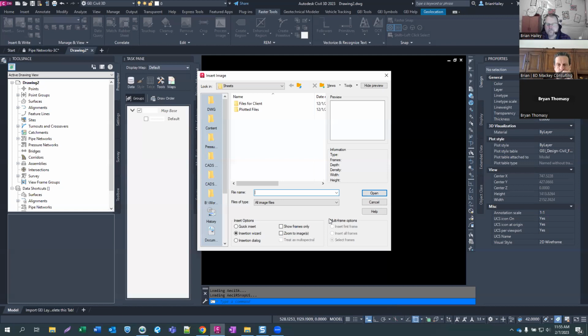Yep, I use the align command, and the 2 items that I pick, if you can find striping or anything that's on the ground, it's got to be on the ground. You don't want to do a chimney piece or something like that, because some of that imagery is skewed because of the angle the picture was taken at. So anything that's on the ground that doesn't cast a shadow is probably a pretty solid bet.